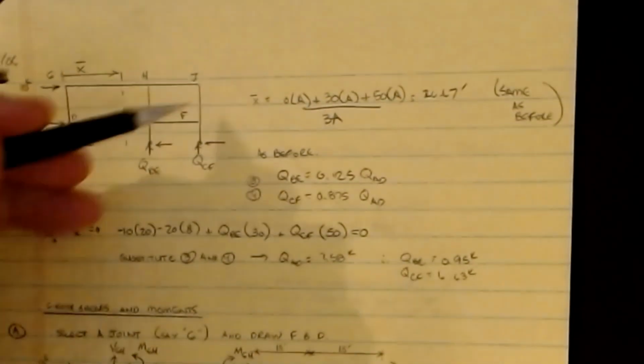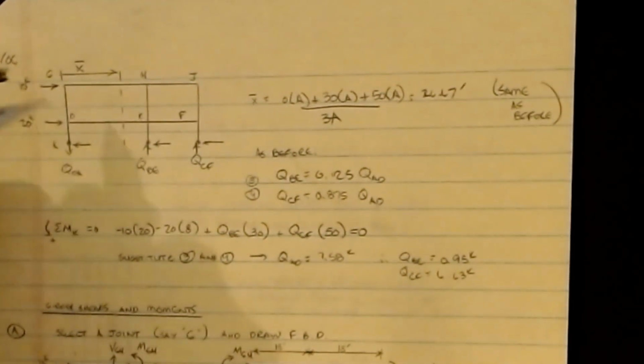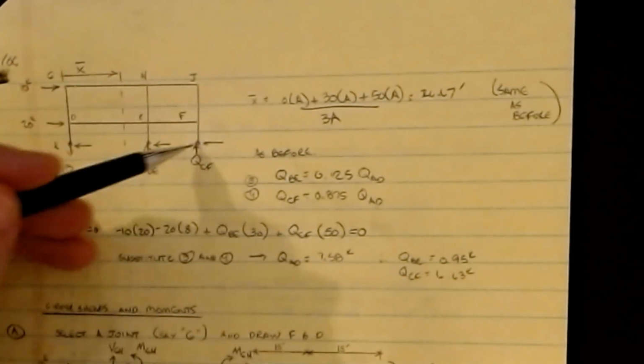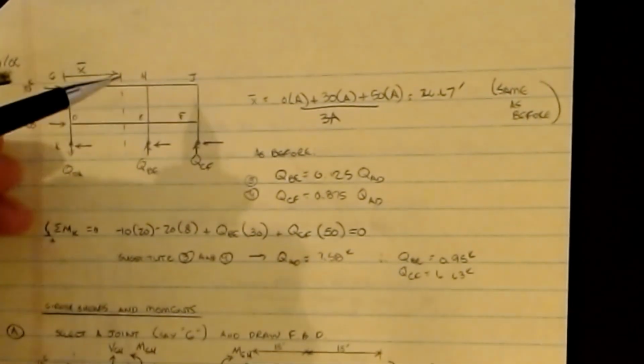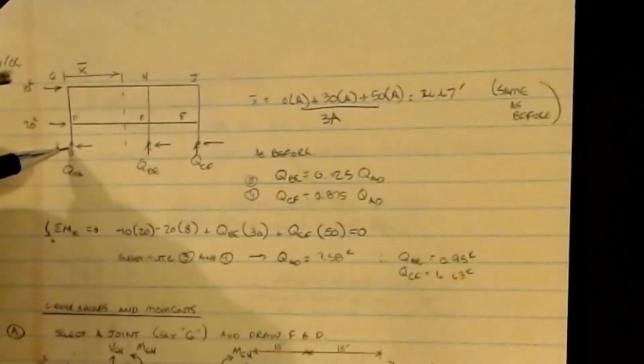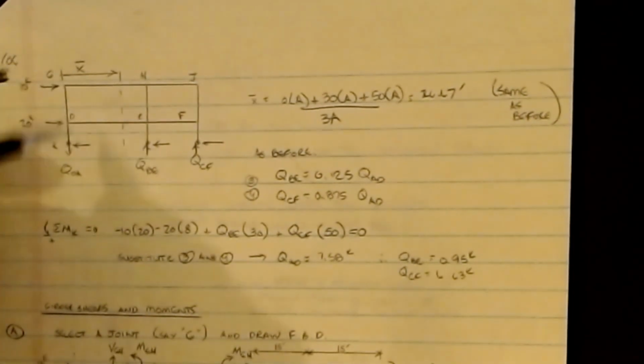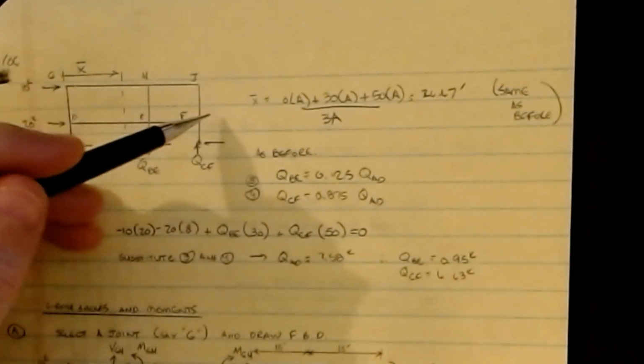Okay, now that was the axial load in the upper piece. What we're going to do is repeat the process for the lower piece. Again, you take everything from the second story, so we go down to the hinges in the bottom floor, and now we have our free body diagram. And again, we're not cutting anything up above, we're keeping it all together.